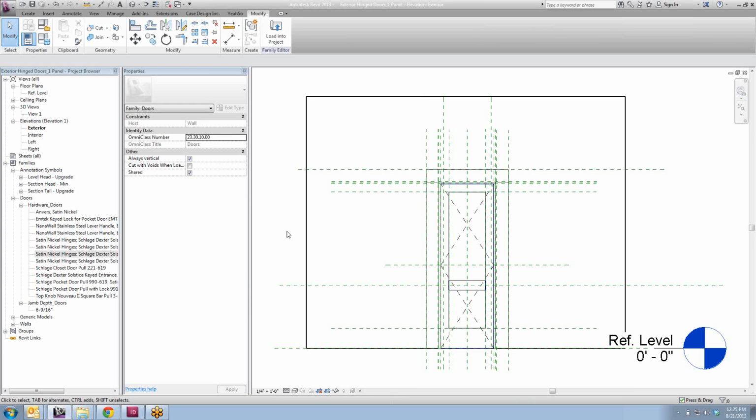We should have a louvered option, as well as solid core and hollow core. Yeah, and that's another parameter, another door parameter like these inside of the interior door families. And so I think we might have to do a doubled up parameter, sort of like selecting the trim and the trim depth, because for a louvered door, you're going to want the visibility to change based on which panel option you choose.